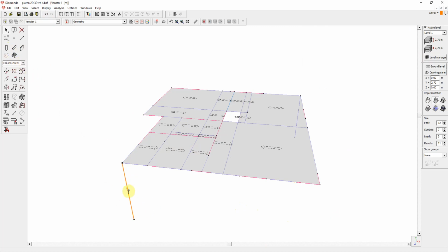The height corresponds with this height from the level manager. The current plate is considered as the cover of the first floor. And now I will continue with the drawing of the walls. You just draw them directly over the lines you want to be turned into walls.